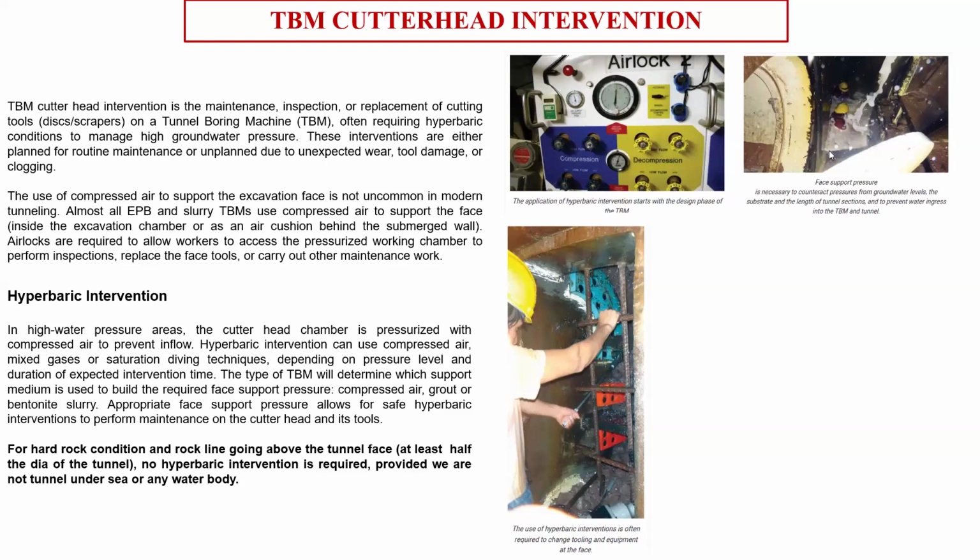This is a very typical case in Lucknow Metro. At the end, for the segments that were settled, we tried to lift them by PU grouting from the bottom. And after the minimum amount was lifted, we made additional grouting to all the junctions of the segments by drilling additional grout holes. And then we made it a watertight structure.